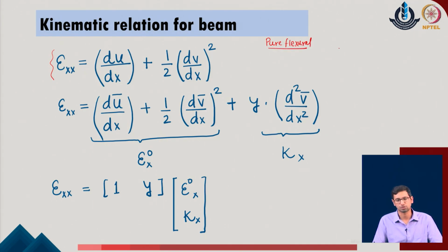This means that the axial change in length of the member is also permitted, and that is a necessary feature of large deformation problems, because the responsible feature which typically modifies the stiffness in large deformation cases is the axial load active on the system. To consider that in the formulation, we have also adopted the axial deformation for the given system.